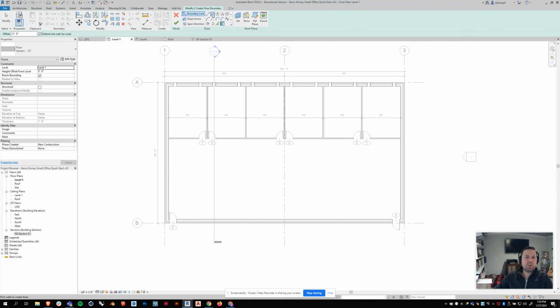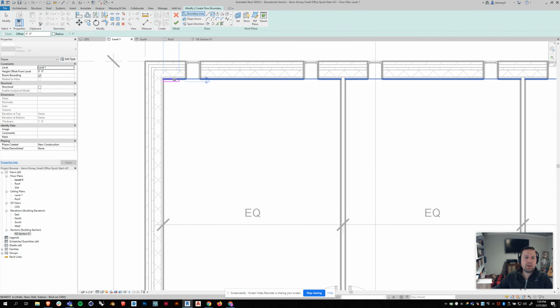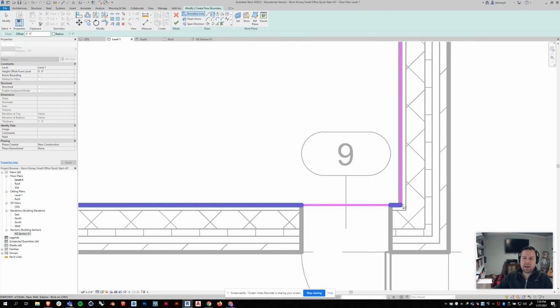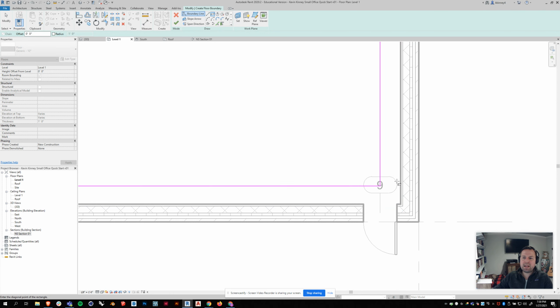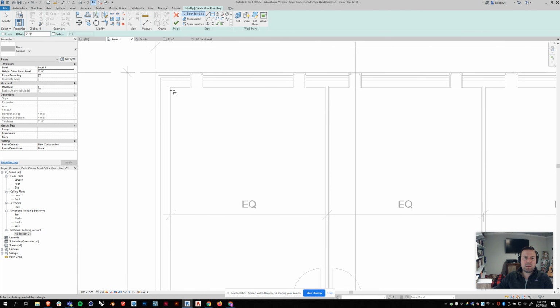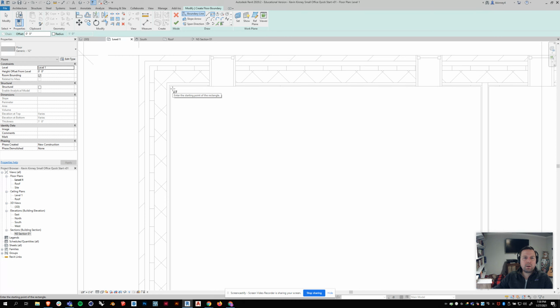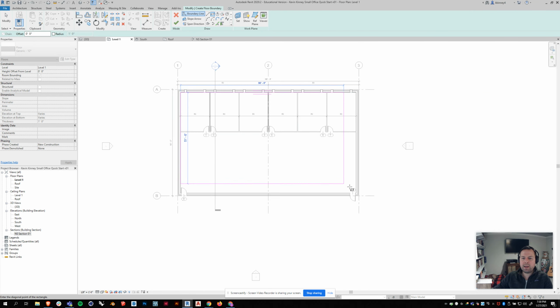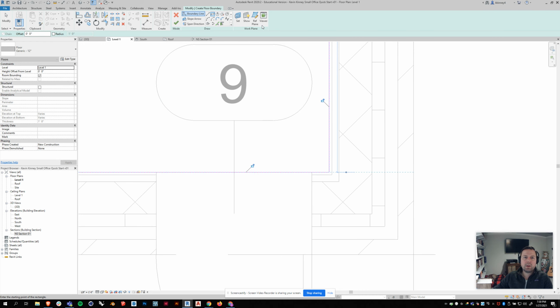Now, instead of doing lines, let's do a rectangle. I'm going to go from the inner edge here to the inner edge corner over here. I want to snap to that corner, so try to be deliberate. If the line weights are screwing you up, you can always turn on thin lines. Oh, it looks like it wants me to start the rectangle over, but that's fine. I'll just do it from this inner drywall edge to this inner drywall edge, you can always adjust it later, and hit the green check.